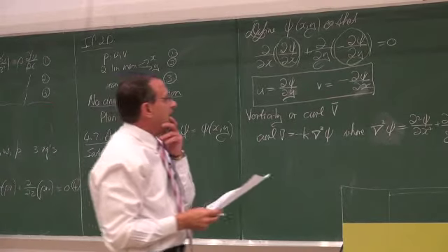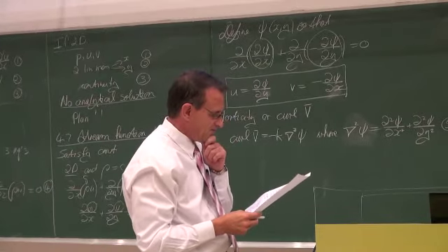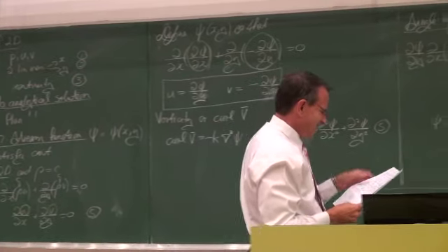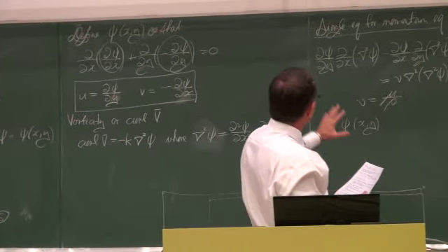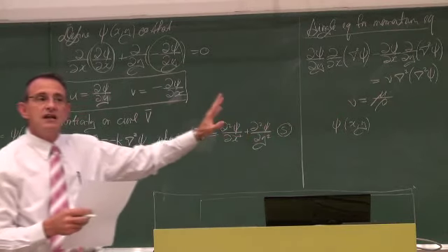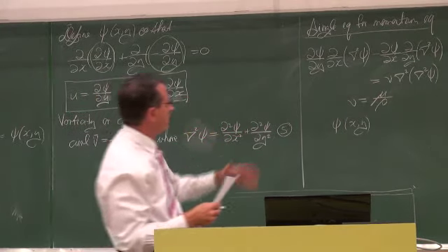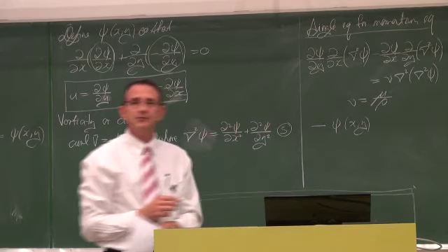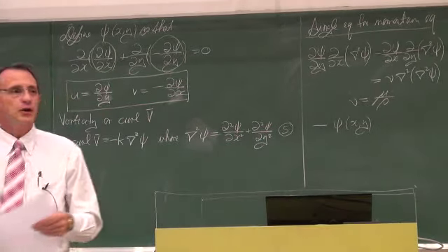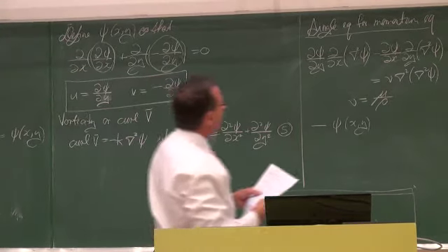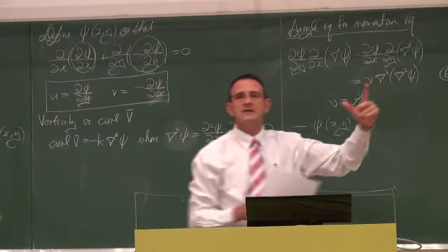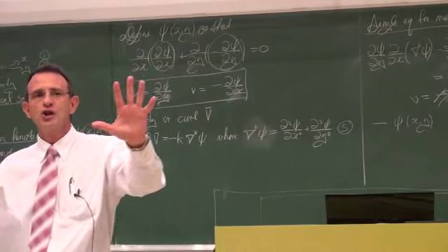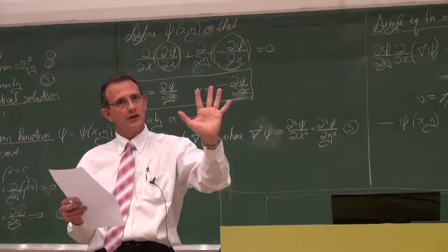Now in a sense it is a victory, and in part a defeat. Okay. It's a victory in the sense that we only need to solve the stream function. It's a defeat because we're now going to have fourth order derivatives, and we're going to need 4 boundary conditions to solve the problem with.